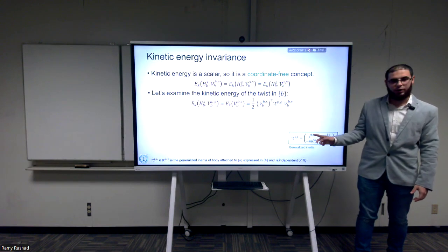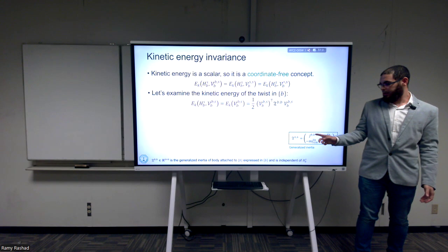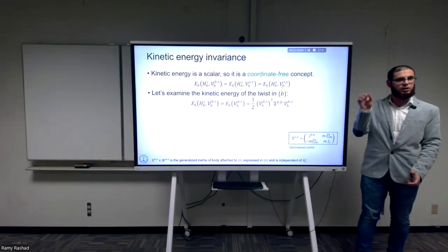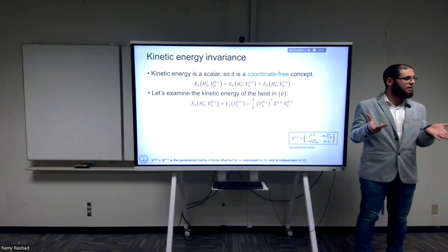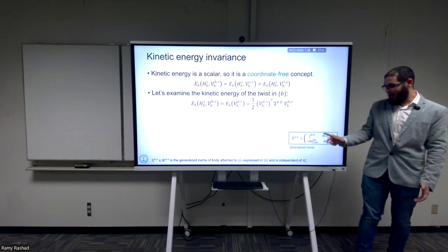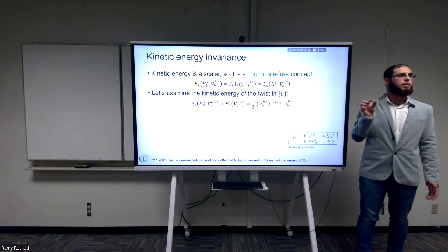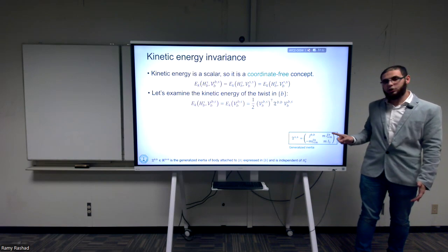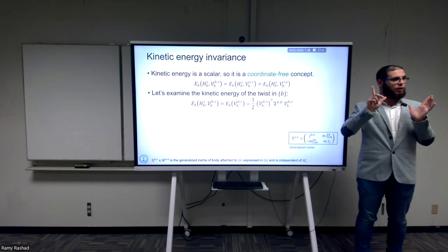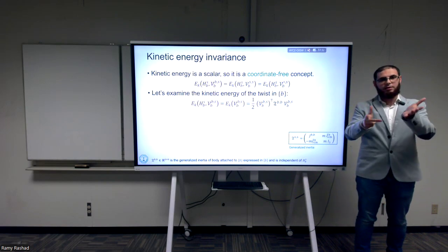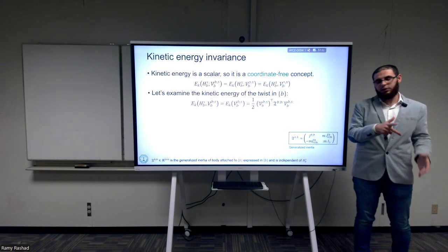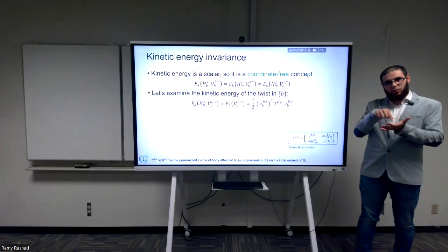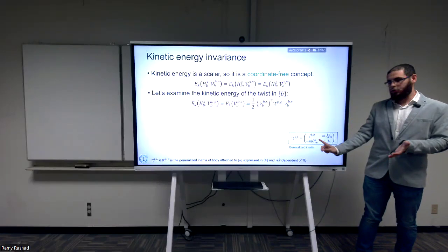In the top left corner, it's a 3x3 moment of inertia matrix or tensor. In the bottom right, we have a 3x3 identity matrix multiplied by m. So it's like m three times, one in the x and one in the y and one in the z direction. They're both the same number. But in the off-diagonal terms, we have something that depends on the location of the center of mass in the frame that you chose. I can choose the frame B to be anywhere. The only condition is that it should be fixed with the body. So whenever the body rotates, it should rotate with it, and whenever the body translates, it should translate with it. But should it be at the center of mass or not, in general, I can choose it the way I want. Where the actual center of mass is located in this reference frame gives this cross term.